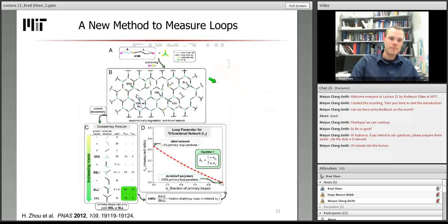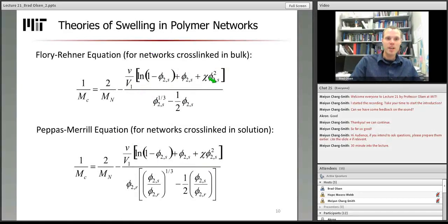As you can see with the Flory-Rehner theory of swelling, there will be some maximum or equilibrium swelling in a gel as a function of its chemical design. If during the synthesis the material crosses over from being below its equilibrium swelling to above its equilibrium swelling, then when the material crosses over, solvent will be forced out of the gel in order to go to the equilibrium level of swelling. This sort of deswelling during synthesis, as crosslinks are added, is known as syneresis and can produce macroscopic inhomogeneities in gels. And this is one of the reasons why many gels appear cloudy as opposed to clear.